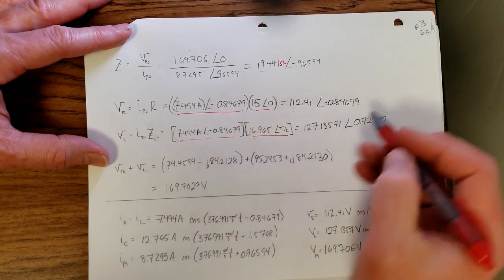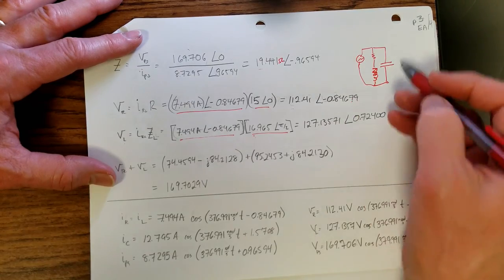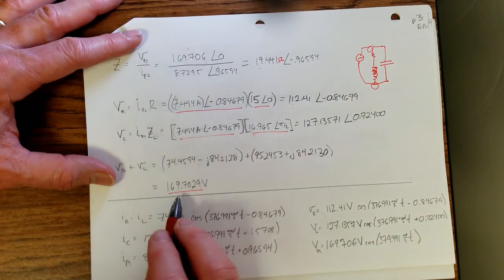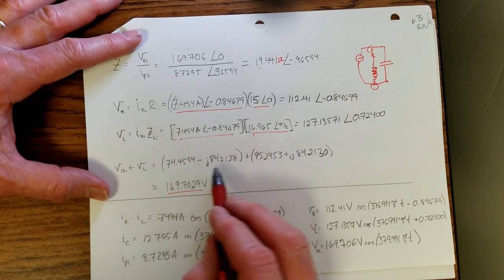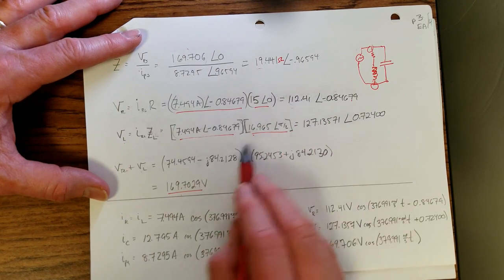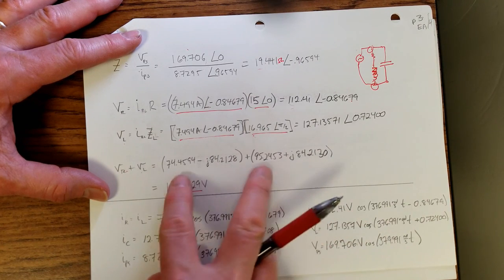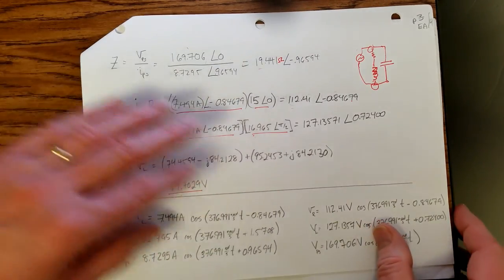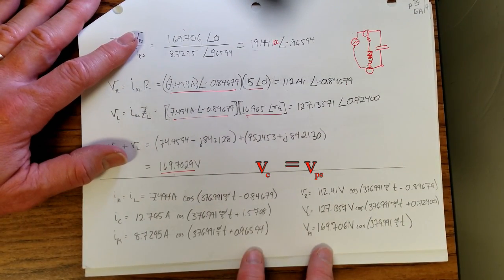And now we're going to check, because the sum of these two should be the same as for the power supply. So the potential between these two should be the same potential going that way or this way, and so I should end up with what I end up with, or at least close enough. But when I'm adding these two voltages, voltage across here plus voltage across there, I put them back into rectangular form again. Magnitude times the cosine, magnitude times the sine, magnitude times the cosine, magnitude times the sine. My two imaginary parts cancel out, and I'm left with pretty darn close to what I had before. I think it was 706 instead of 7029, 706. And so now I have my equations right here.